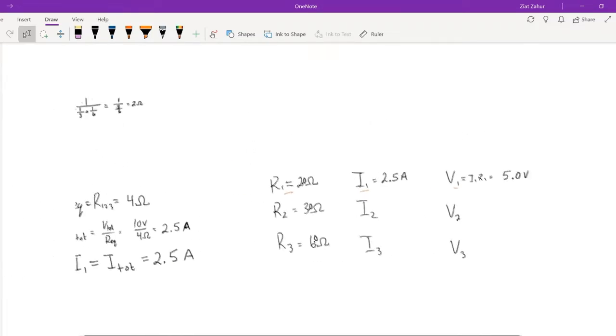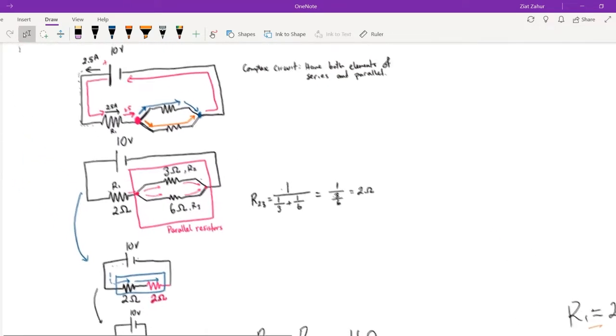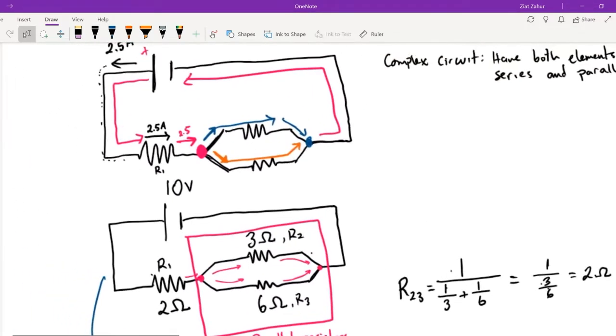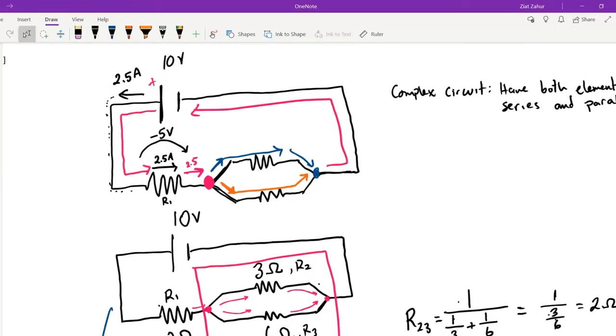So if the first resistor drops 5 volts, after going through this resistor, we're losing 5 volts. Remember, a resistor uses up the electrical potential energy. So since you started with 10 and you lost 5, it's like starting with $10 and now you've paid $5 already.